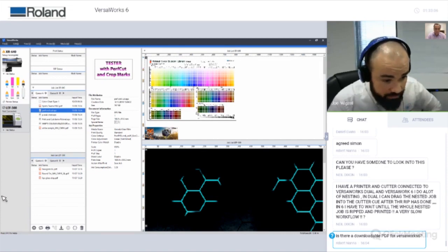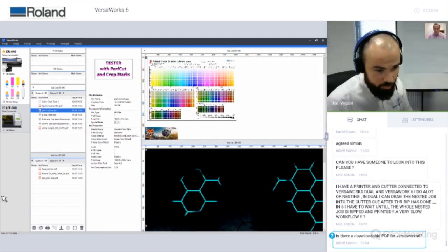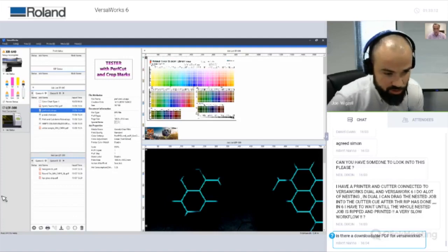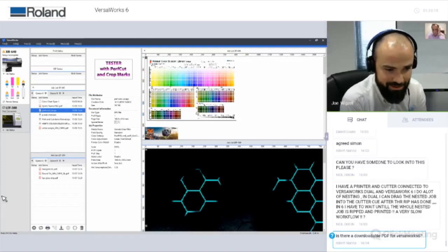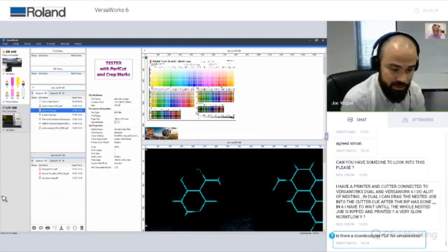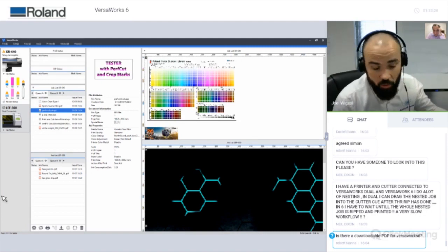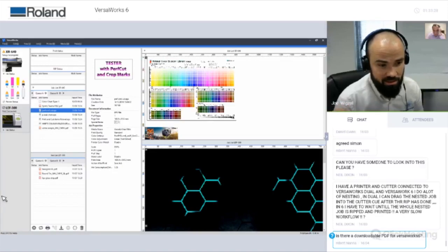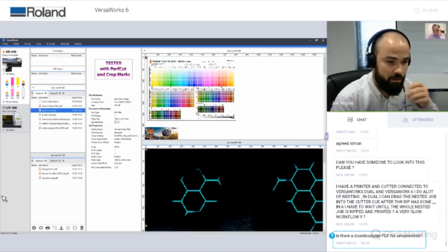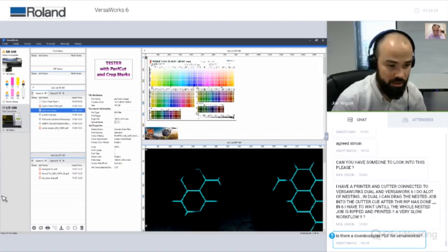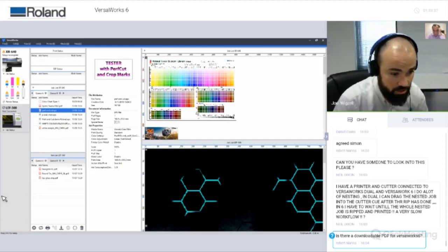Simon. There you go. Yep. How can you enable perforated cut? Thanks, Peter. You've been answering in my absence of talking away here as well. Yeah, you've got to enable perforated cut in your design. Then the option to add perforated cut boundaries comes up. So an option might be to just add a tiny bit of data into your file that is perforated spot color, and then you'd be able to add the cut boundary.